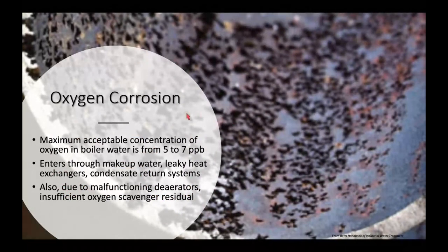Now, as for the oxygen, well, we know about this. Really, all this stuff ultimately is galvanic in nature. Even the stress corrosion cracking, it's all galvanic in nature. And all we have is a whole bunch of things that exacerbate or promote corrosion, whether it's dissolved oxygen or whether it's hydroxide or whatever the situation is. We just got something going on that is accelerating the galvanic corrosion. And that's what we see with an oxygen pitting, oxygen corrosion cell.